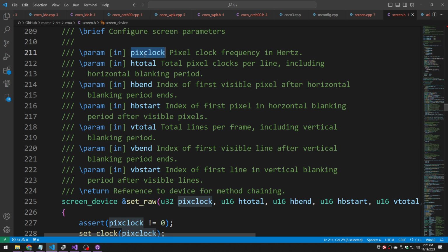But what's a pixel clock? You're not going to find that in the 6847 datasheet. The pixel clock is the frequency it takes to render a single pixel. The key is to find a multiplier for the VDG clock that will transpire over the course of a single pixel and provide the least, hopefully 0, amount of round-off error. So how on earth do I figure that out?